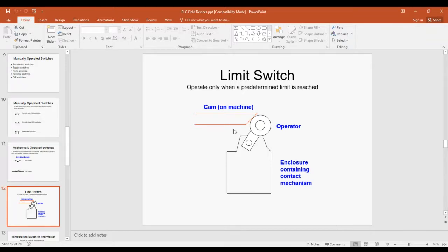I actually used this in a system. I was fooling around with electric windows on the car. I had a thermal sensor, and I was trying to have the windows lower themselves when the car reached a certain temperature. I built this device with this exact limit switch on the side of the window. The wheel was against the glass, and when the glass lowered past the bottom of the wheel, the switch would disengage and the motor would let the windows down. But the problem was I kept current going to the motor when the window was down, because I didn't yet know how to build a circuit to shut the motor down when the current built up at the end of its limit. Anyway, a limit switch.